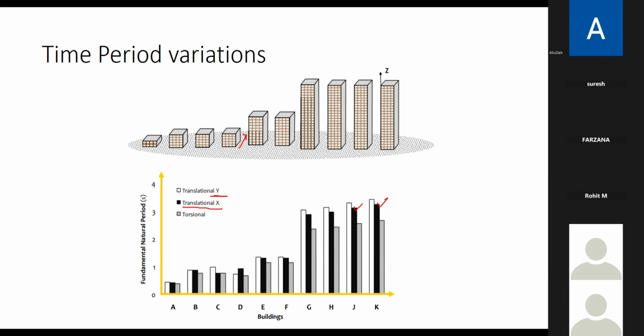Also we found the torsional frequency, the rotational frequency. When we solve the analysis, it will give us the result. We have nothing new here, we just analyze and see the mode shape. If the building is deflecting in this axis, in this manner, it is the bending frequency, your first frequency in the x-axis. If at the top, my building's mode shape is rotating in this axis, twisting, then we call it a torsional mode shape. Corresponding to that mode shape, we find the frequency, and that frequency has a natural time period.